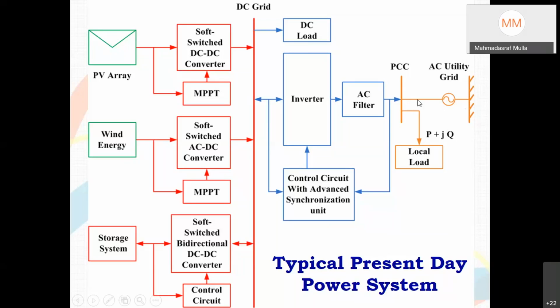To give an example, a brushless DC motor will give you more torque per ampere if you give quasi-square wave current instead of sinusoidal current. So for such a load, there is no meaning in analyzing the stator current and talking about the THD of that or power quality issues related to it. So power quality will be of major concern where utilities interface and AC power control we want to control. Okay, so that is what I understand. If you have some other view, you may comment.